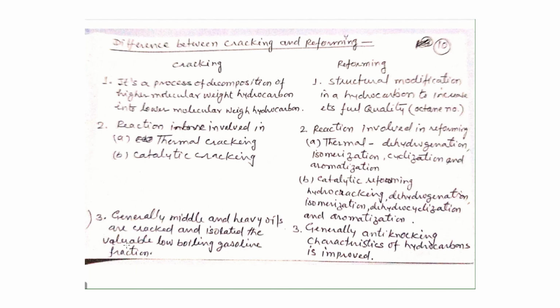In cracking, generally middle and heavy oils are cracked and the vapors of low boiling gasoline fractions are isolated, while in reforming the anti-knocking characteristics of the hydrocarbon are improved.